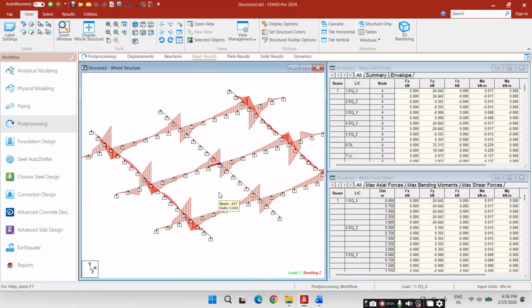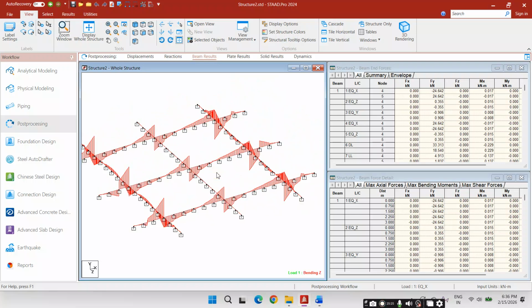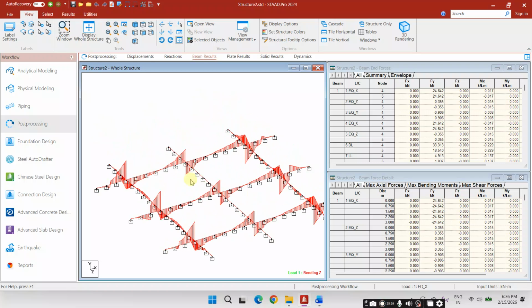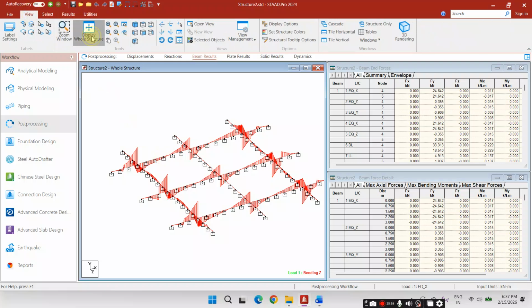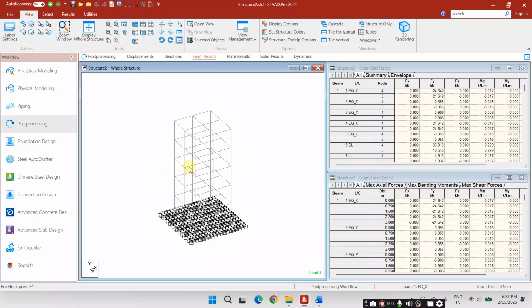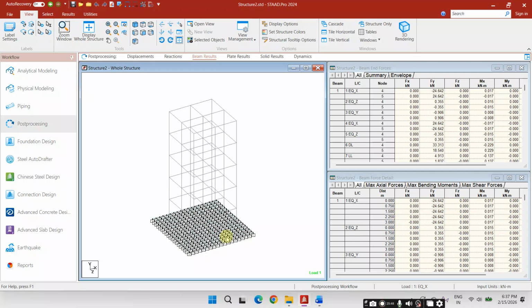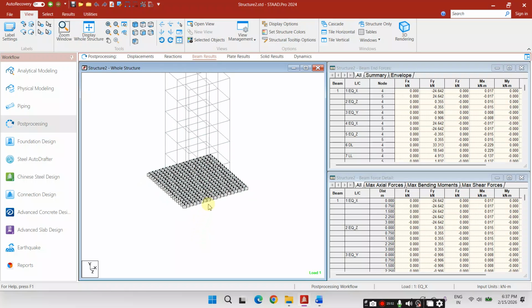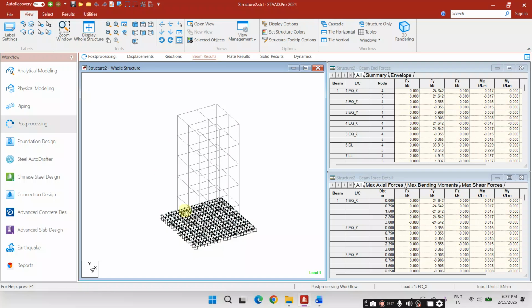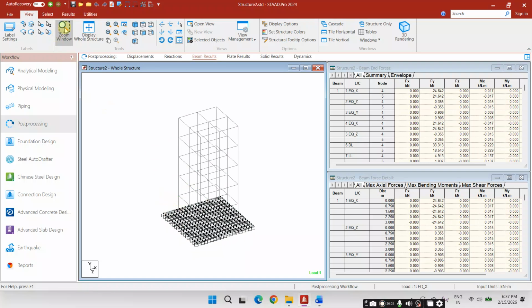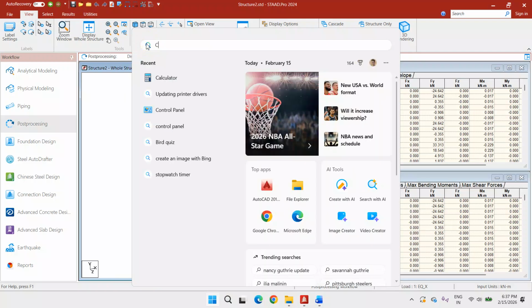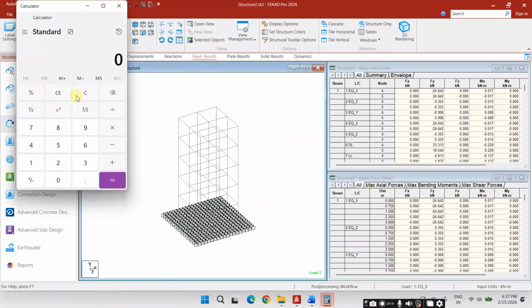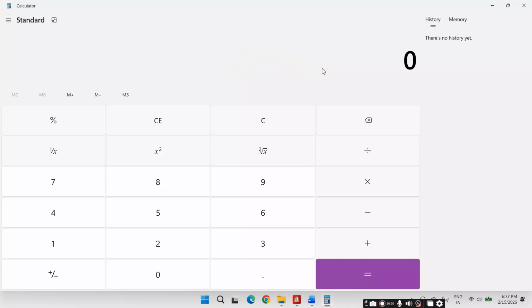You can see, and you have to mind it firstly that the raft slab should not cross the bearing pressure, means actually I am to say the pressure due to structural load, the pressure beneath the foundation should not be greater than the gross bearing pressure. I mean, if the safe bearing capacity